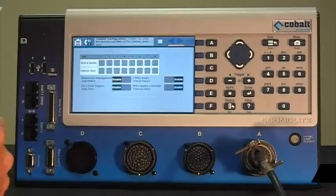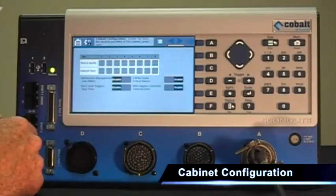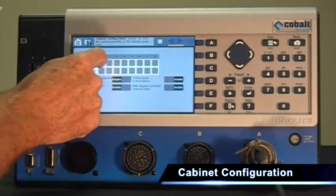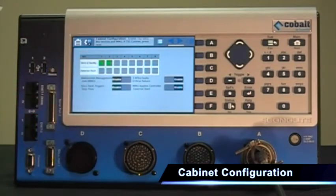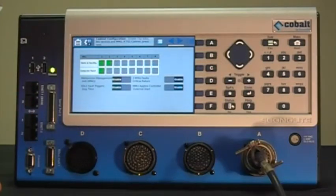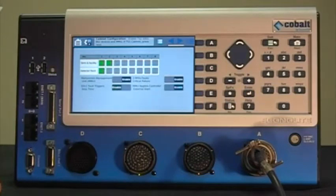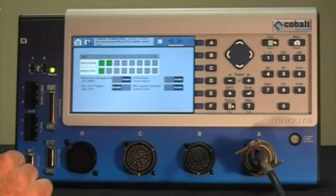So the first thing we're going to do is set up the cabinet, and this is a TS2 Type 1 cabinet. Let's add BIUs in positions 1 and 2 in the terminal and facilities, and let's also add one in one detector rack. We're also going to have an MMU, so we'll touch there to enable the MMU. Okay, let's go to the next screen.